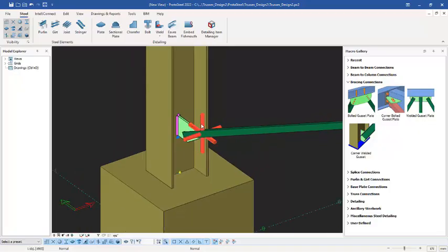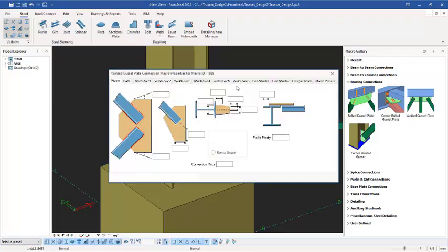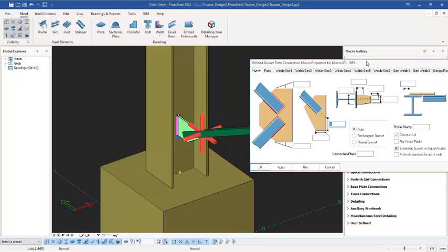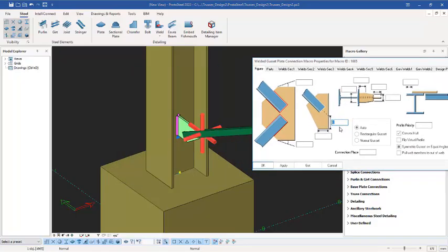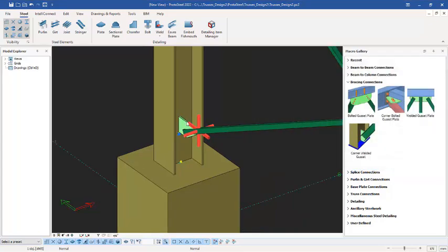Alright, if you double click on this now, I want to show you something. A dialog will come up just like this. You will notice this provision I key in as 0. If this 0 is not there, maybe I get rid of that and click on apply, look at the way the plate will be. So this is not neat at all. That is why you have to feed in 0 here so that you don't have an excess plate. Once you enter 0, click on apply, you have that. So click on apply and okay. So we are done with that.